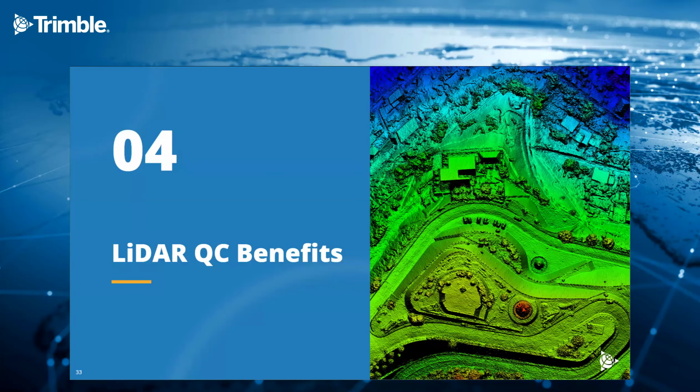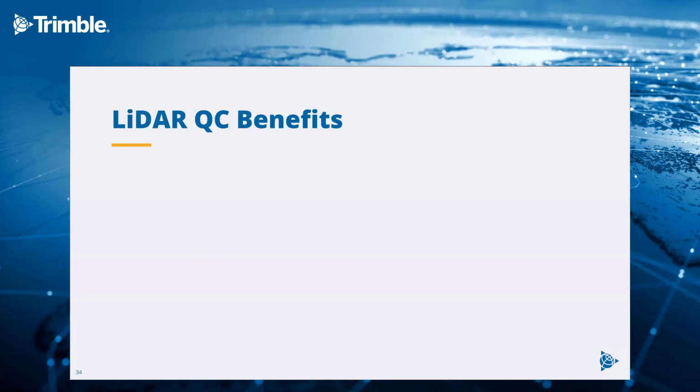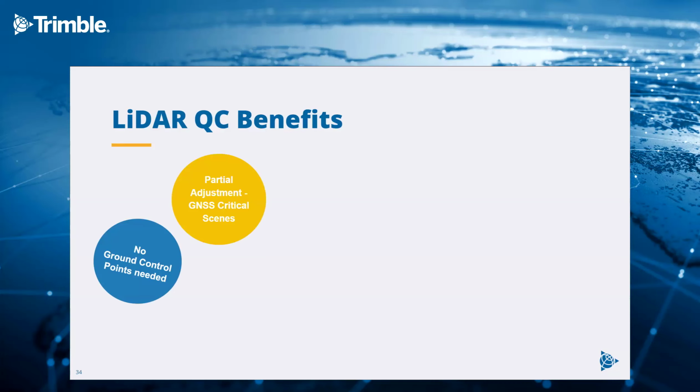So let's get to the LiDAR QC benefits. As I said before, LiDAR QC does not need any ground control points right now. It does a good job without it. We support a partial adjustment, so LiDAR QC can focus on very critical themes. It does not need to run over all of the data that you collect.